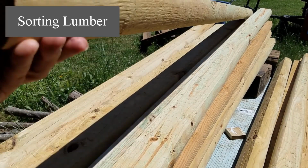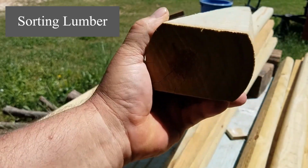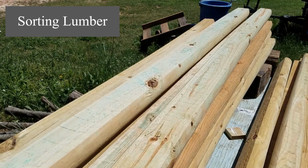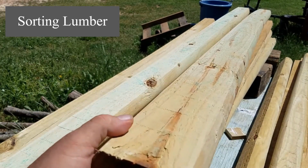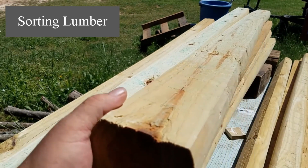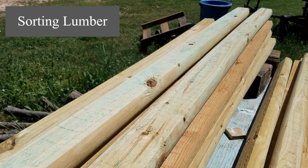So we would want to sight down all these boards, and you can see that board right there is pretty straight. So we could use the straight boards for the 8-foot, the long cuts. But then you can look down this board, and you see that board is crooked. All right. So what would we do with it?